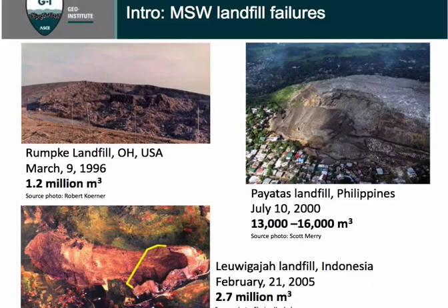Well, why I say take good care of landfills is because we know from time to time landfill failure will happen. Here I show 3 different photos for 3 pretty famous cases of landfill failures. The first one on the top left is the Rumpke landfill failure, which happened in Ohio. It's primarily due to weak interface shear strength between the solid waste and the clay liner, which ties back to some of the other presentations today.